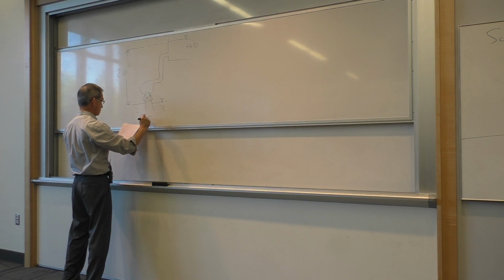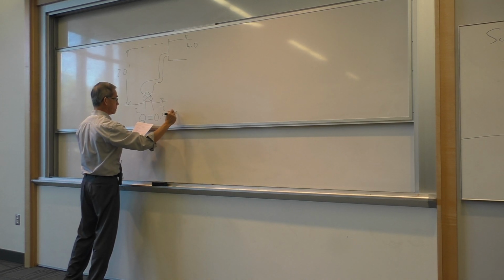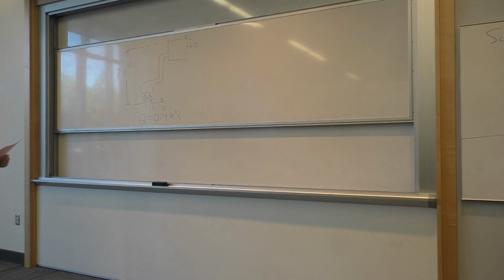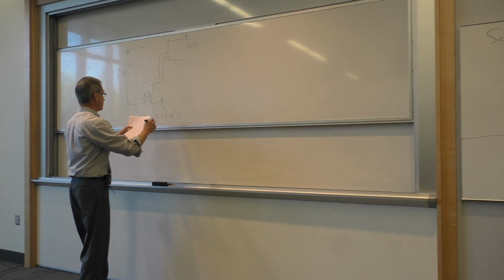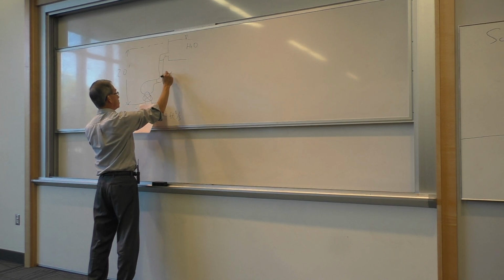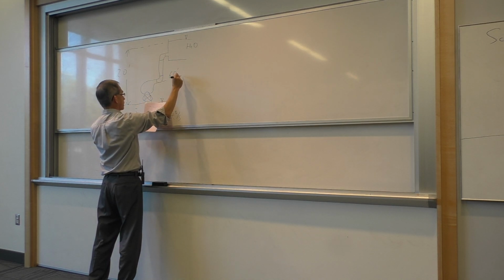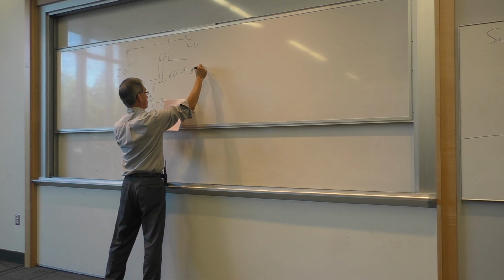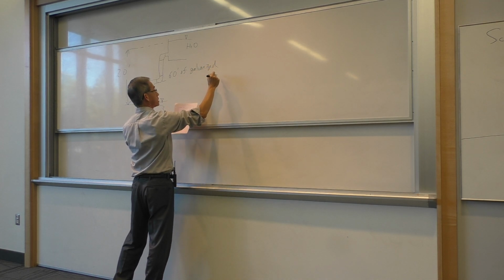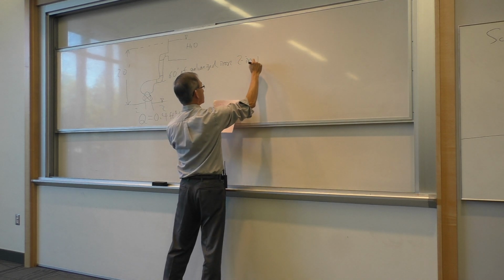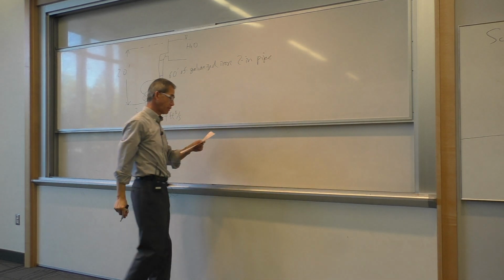The flow rate is given, just like that schematic or roadmap. We're going from left to right, so the geometry and the flow rate are given. So this flow system is a little complex. It has two 90-degree elbows, and the plumbing consists of galvanized iron, 2-inch diameter.